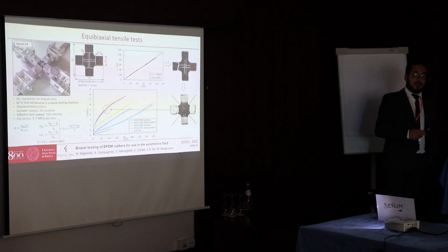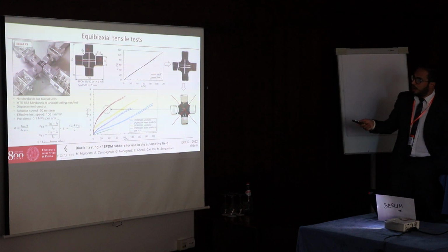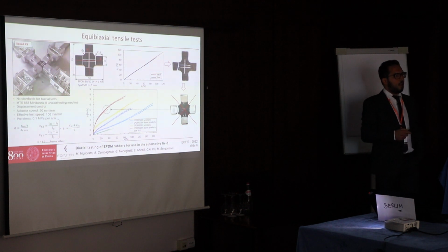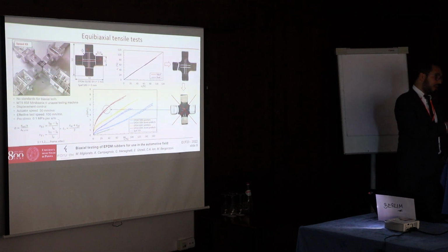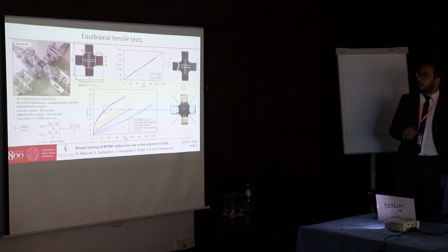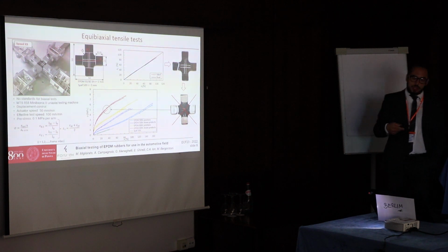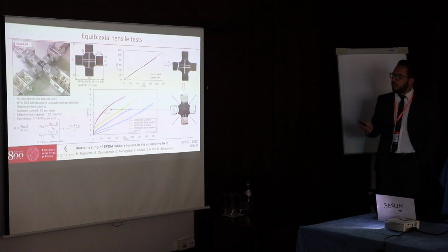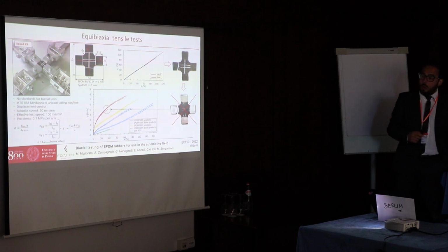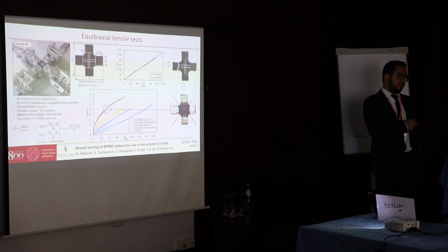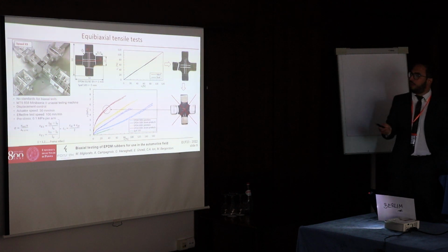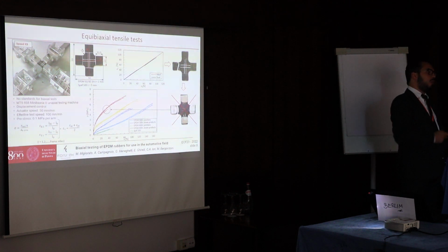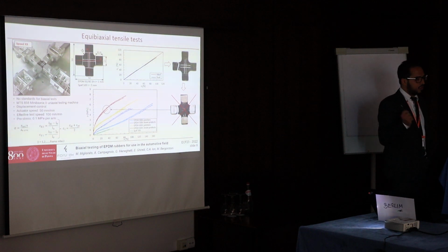Yes, thank you. It is a very good idea, and people who tested rubbers under biaxial tensile loading in the literature commonly use the specimen geometry that you suggested. However, we had some problems with the company manufacturing such a specimen geometry due to the molds that we adopted. There would be an additional mold with cutouts. But yes, it's a matter of optimization.